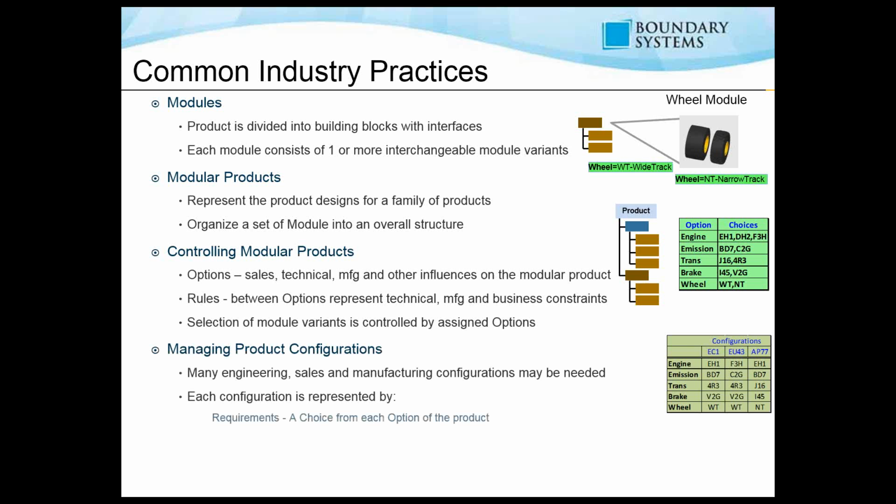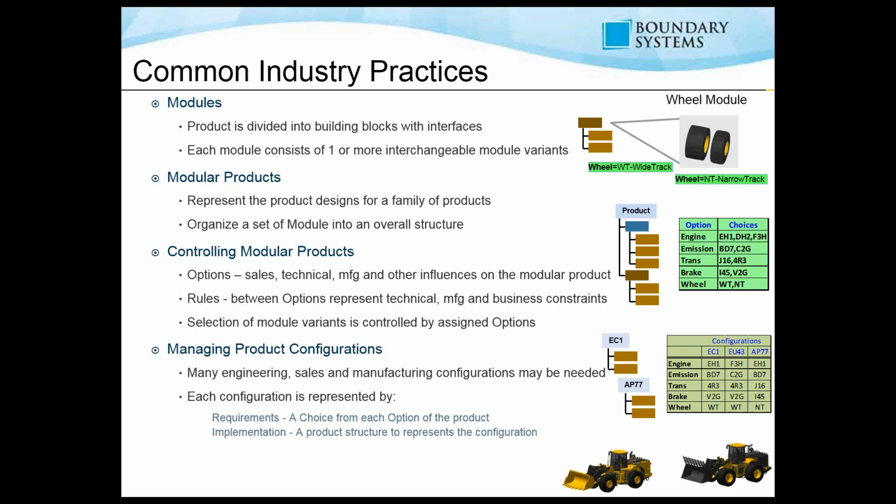And then, of course, managing your product configurations. Many engineers, sales, and manufacturing configurations may be needed. Once again, we can go into the assembly itself and just save them within the assembly and be able to access them from the variant builder because we've already stored those. Or we can go through once again in the variant builder and at some point bring those out as separate assemblies.